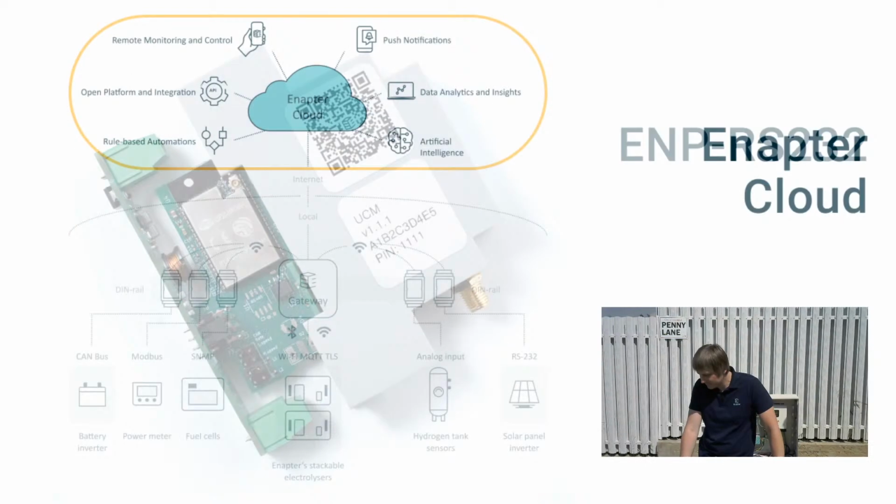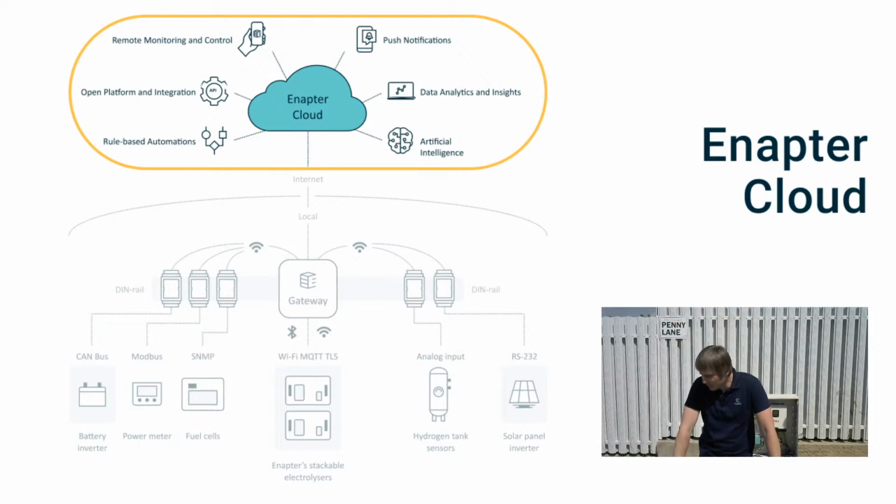The question from Paul: how is the electrolyzer controlled, modularity, parity load? Okay, this is a very good question. The electrolyzer can run at different production rates. In general, you can set up the production starting from around 20% to 100%. There are a few options for this. One is to utilize the Modbus interface of the electrolyzer, or the second one is to use our EMS.